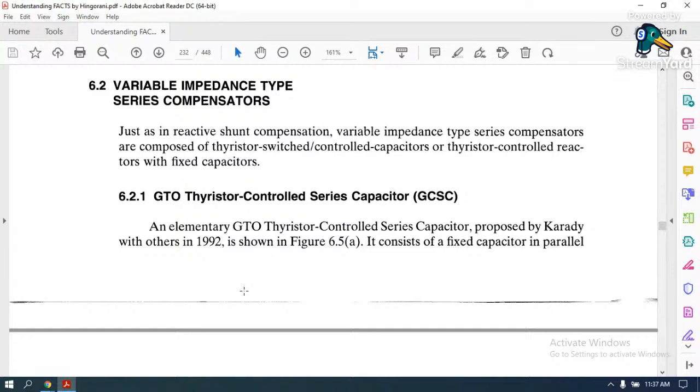Now, for a short transmission line, it is okay to connect a series capacitor, but for a medium or a long transmission line, you need to connect one shunt inductance also. Because as we are cancelling the net inductive reactance of the transmission line, the connected capacitor as well as the capacitance formed between line and ground will both try to generate reactive power and inject it into the transmission line.